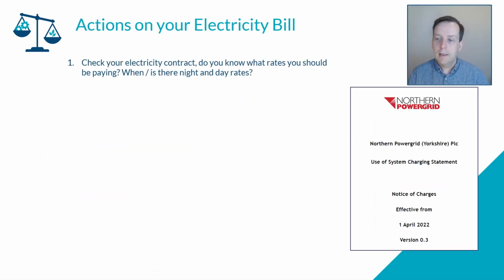So, sidestep, there is a change to how those two systems are operating. So those DUOS and TUOS, the distribution and transmission charges, they are changing to a more capacity-based charging rather than use charging, because a lot of businesses have been managing their energy in order to avoid the triads by reducing consumption and such things.